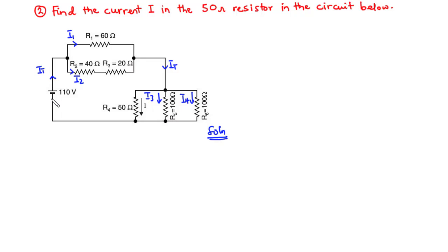So let's try to find the total resistance for this circuit. So we have these two resistors connected in series because we have the same current flowing through them. So we are going to have this to be 60 ohms. Now these two resistors are connected in parallel. Whenever you have two resistors connected in parallel which are of the same value, then the parallel combination is basically half of the value. So we can have 60 parallel 60, which is equal to 30. Now remember that when you are solving any question or doing an exam, try to do the correct calculation, that is 60 times 60 divided by 60 plus 60, to arrive at this value.